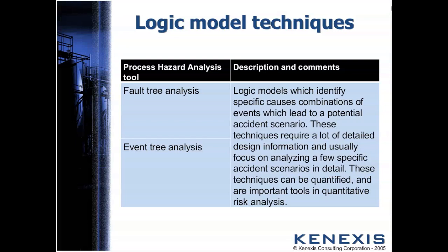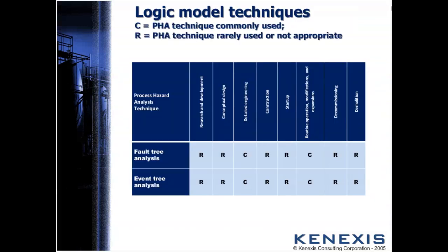So a fault tree can model virtually any plant process failure scenario, and it's also capable of modeling some scenarios that are not possible with other models, such as systems where both the equipment failures and the human failures are important, or where the overall system requires component failures to occur in a certain sequence. It's about the only tool that does a really good job of evaluating that complexity.